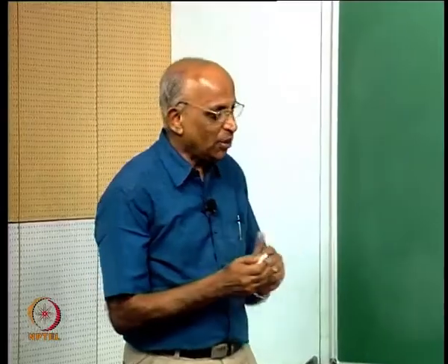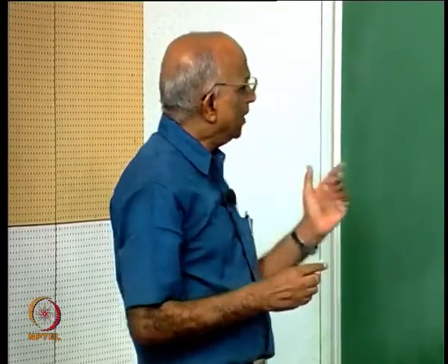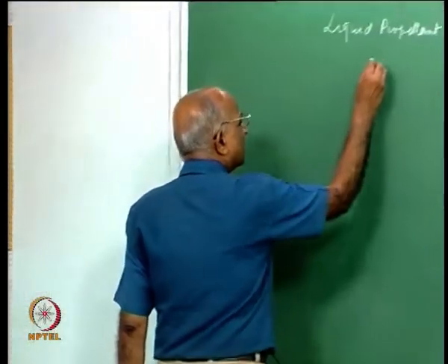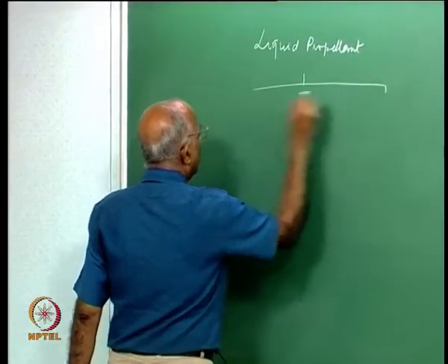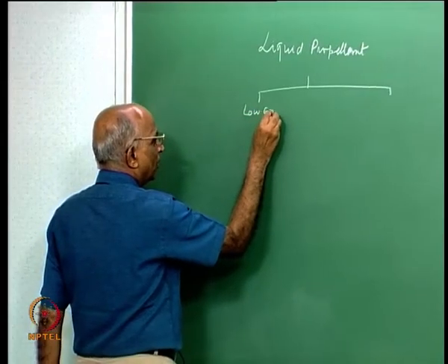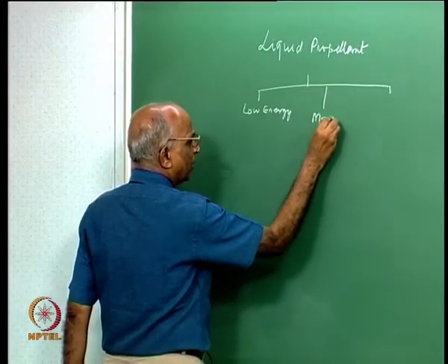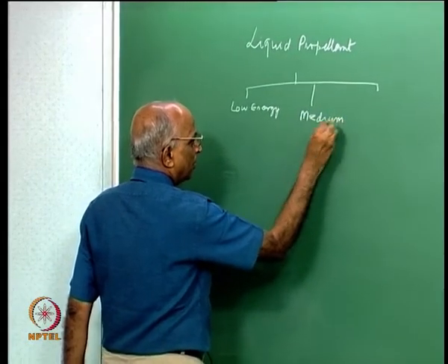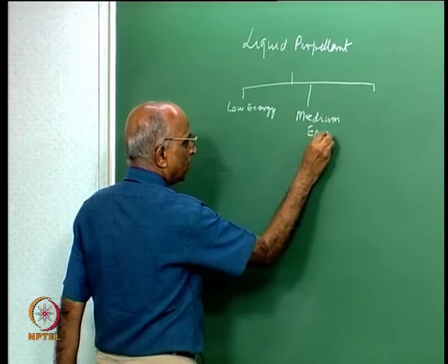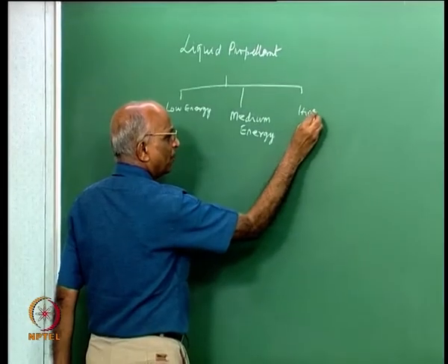While we classified solid propellants into double base, composite, a mixture of composite, that is composite modified double base, and nitramine propellants, in the case of liquid propellants we had a somewhat different classification. We told ourselves the propellant could be a low energy propellant, or a medium energy propellant, or a high energy propellant.